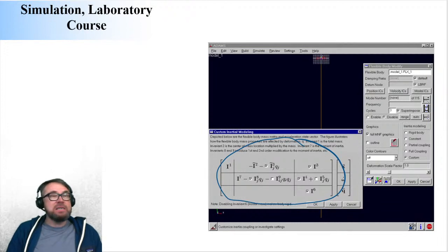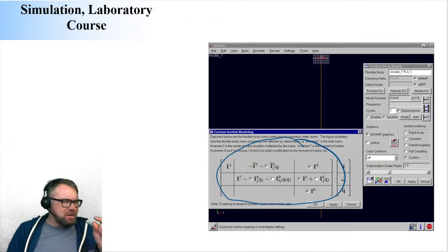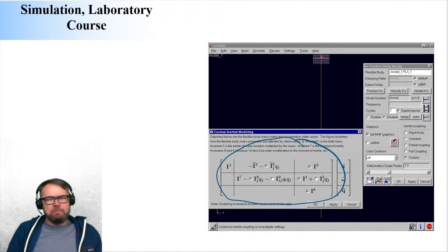Because partial coupling increases computational efficiency very significantly. You can make the computation much faster, but you will also lose a little bit of accuracy. How much? No one really knows. So you're kind of stepping on thin ice because you don't know if it is able to hold you or not. So my recommendation again: keep them all fully coupled, then face the consequences, which is just a slightly slower computer, but that's what it is.